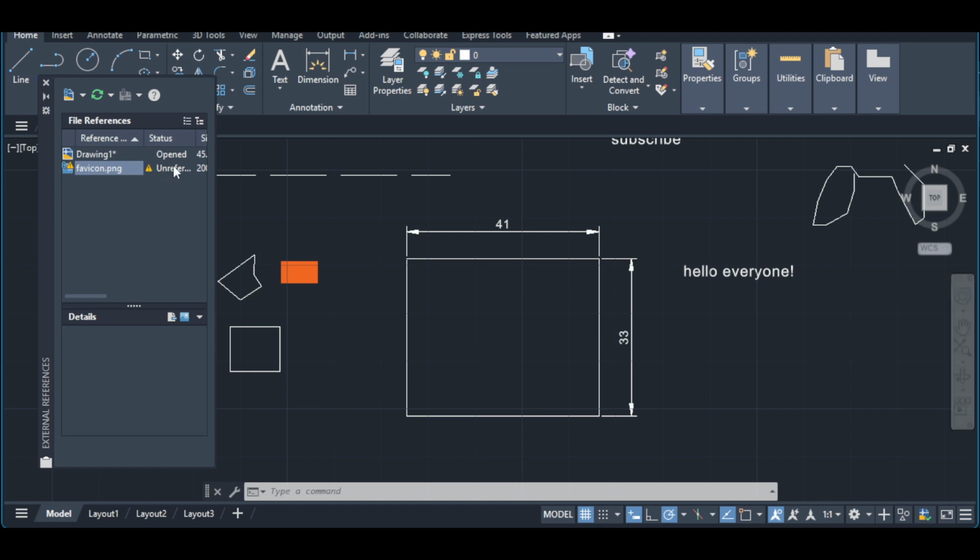That's the core of creating and using XREFs. Open the External References palette, attach the DWG you need, and leverage the palette to stay organized and up to date.